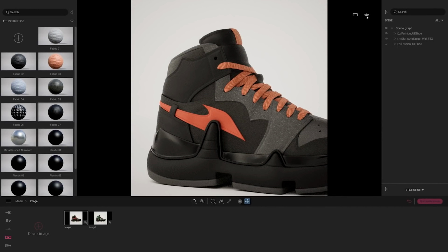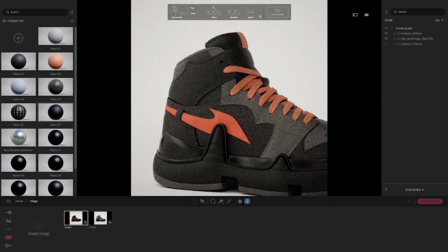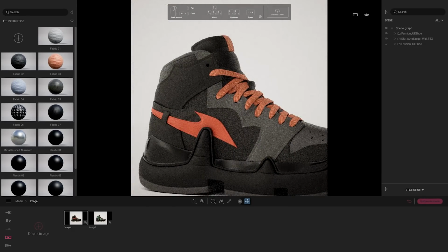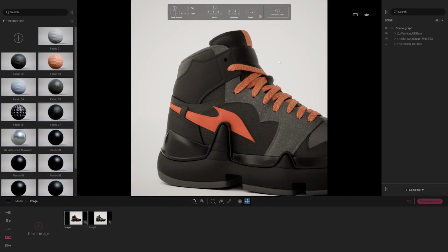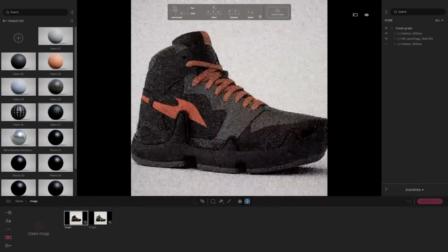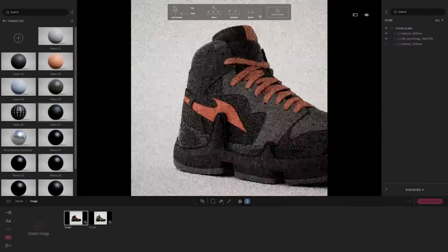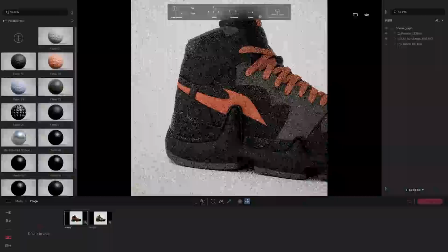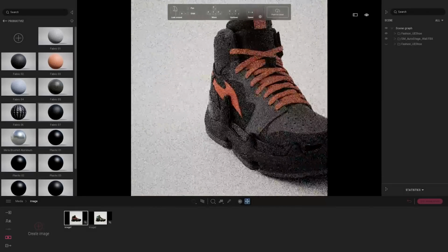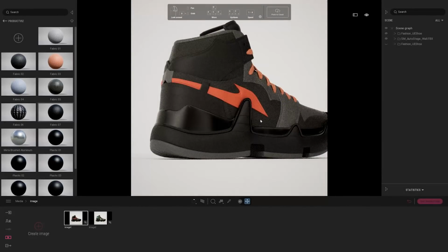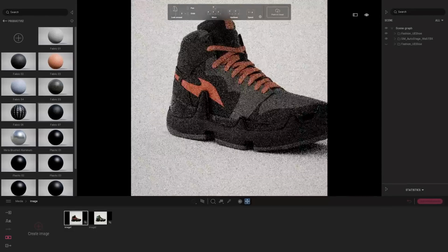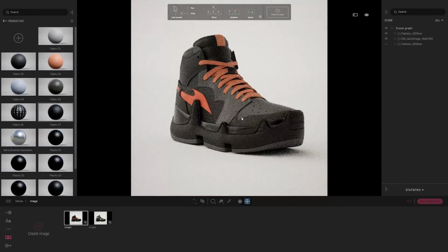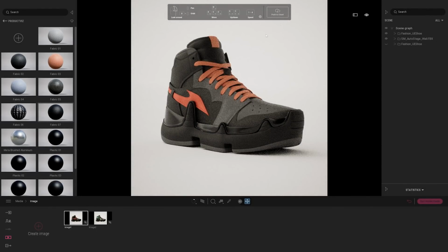By the way, talking about navigation, let's click on the eye menu, and here we have the navigation bar that I'm going to show. Here you have all the basic shortcuts that will help you get started in navigating inside Twinmotion. So here I'm using WASD to move around my object, and I'm using Q and E to move up and down. I can even use arc rotate and orbit or pan to move better near my object. So I don't need that right now, so I'm just going to hide it.